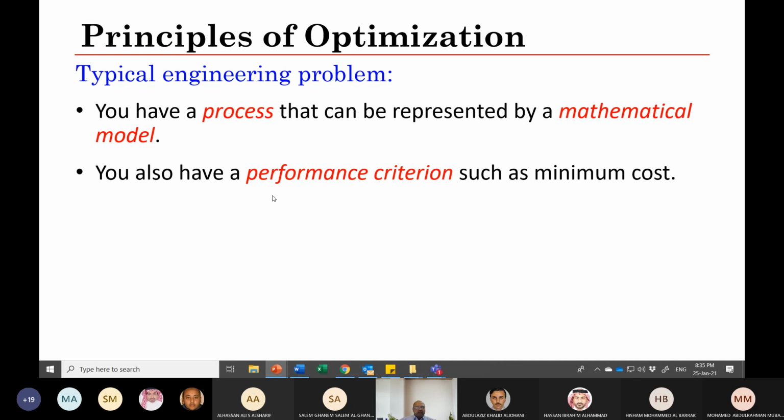it is in the right-hand side or left-hand side, you need to push, and you can define a performance index to search for the controller parameters that move the eigenvalues to the left, or you can put it in whatever area in the left you can have, and you can design your controller to set the eigenvalues of the closed loop system within this D shape.